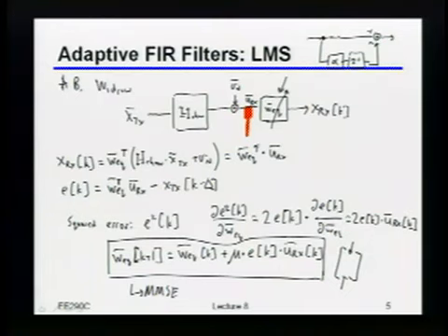So does the delta accommodate only for the time shift in the channel, or does it compensate for the number of taps that are behind? This delta is really compensating for the time shift of the channel. Okay. Right, but I guess what I'm trying to get at, and unfortunately this is a slightly bad example, in reality if I was tuning both of these, maybe it would be more clear. Right, if there was, let's say, an alpha and a beta there, then basically for the alpha, all of these k's would line up. But for the beta, when I move one down in the vector, that's one bit ago. Okay, and then again, when I go to the next sample, one bit down is one bit ago. Does that make sense?